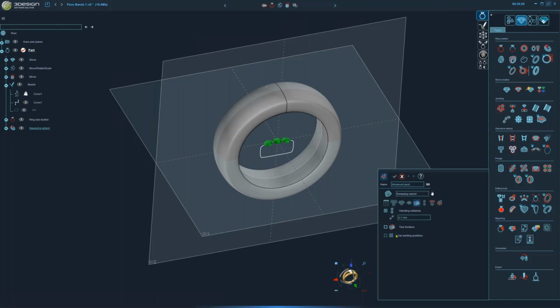So I'm going to use my collisions 0.1. I don't need frontiers because I'm not worried about any of the edges on my topology here getting in the way. So we'll go over to symmetry because it is a symmetrical pattern. I'm going to do a planar symmetry. And we'll do a plane list. I'm going to do the OYZ.